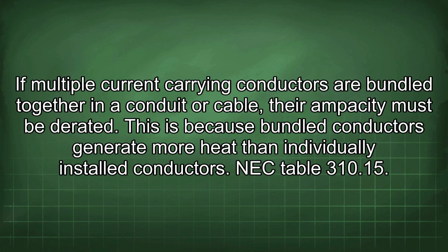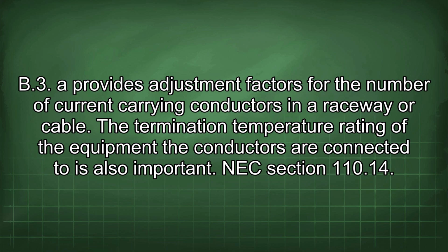If multiple current-carrying conductors are bundled together in a conduit or cable, their ampacity must be derated. This is because bundled conductors generate more heat than individually installed conductors. NEC Table 310.15(B)(3) provides adjustment factors for the number of current-carrying conductors in a raceway or cable.